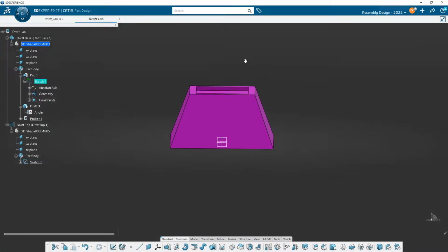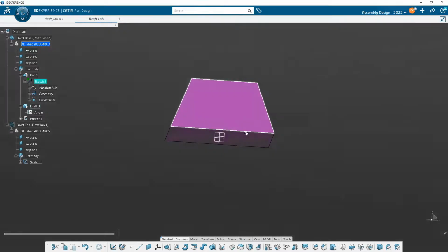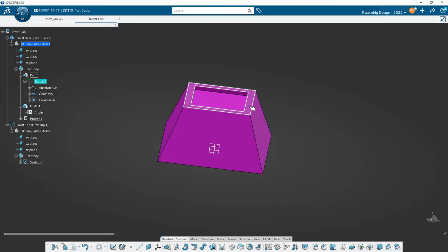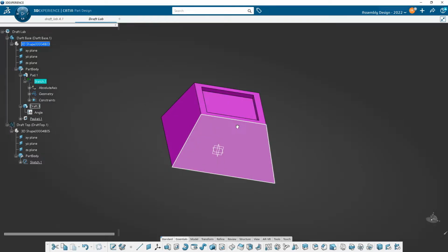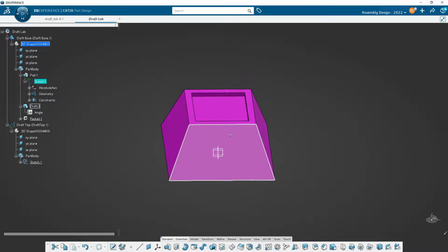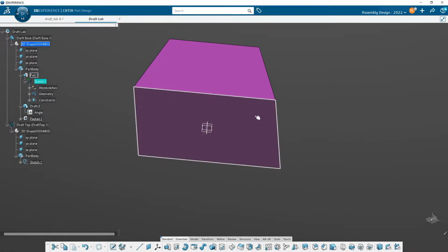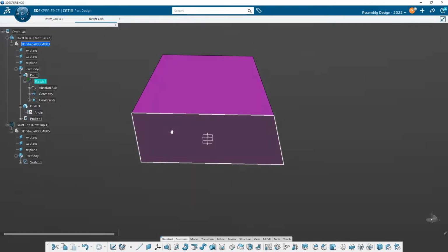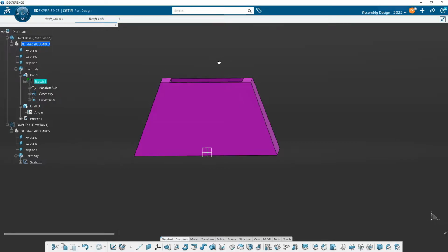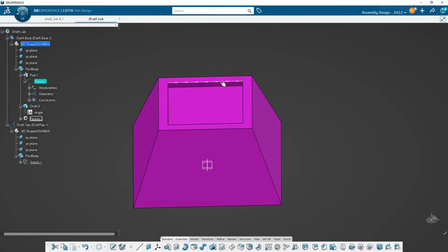If we would have decided to draft it from the bottom inward, okay, then this top will have a dimension that I can probably tell you is not going to be a nice even number, because let's say this bottom one was 50. See if this makes some sense. If this was 50 and we angled it in, drafted it in 20 degrees, 23 degrees, whatever it was that we picked, this square up here is going to be some strange measurement.